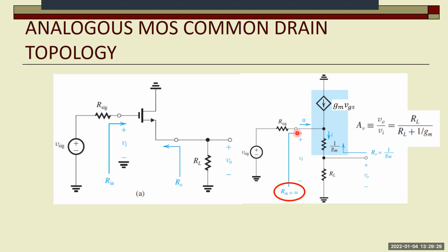That brings the gain to the input voltage is the voltage appearing here. So it should be this series resistance here multiplied by the current divided by whatever is at the output. So RL divided by RL plus 1 over gm. So instead of RE, we have 1 over gm right now. So that's the analogy. Do you see it?